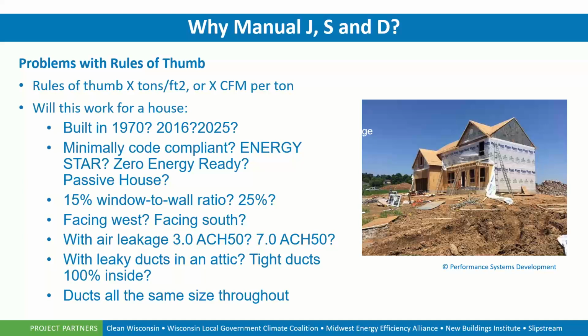So how can we determine the heating and cooling requirements based on what we've done in the past? Sometimes we'll be correct. More often, we're able to alter the HVAC equipment that could be installed when we do a Manual J, versus saying we know that for a home of this size in the past, we put a 3-ton air conditioner in with a 72,000 BTU gas furnace. That's what we're going to put in and just put 7-inch distribution lines to every room. That may cover it, may not. It could be detrimental to the home.